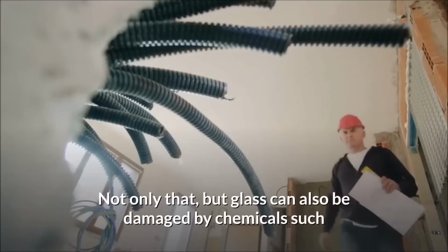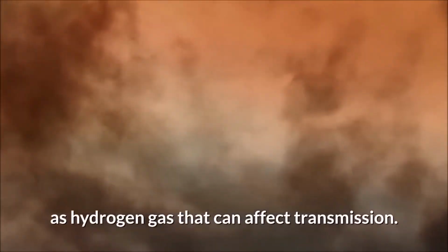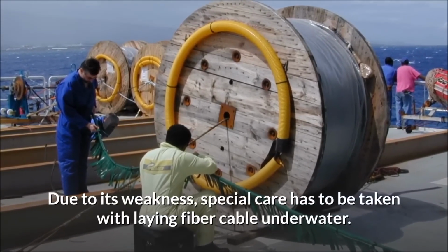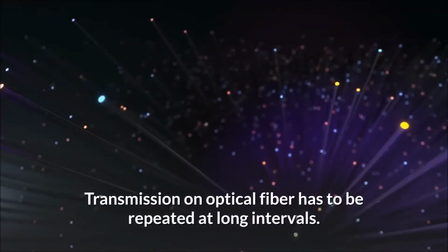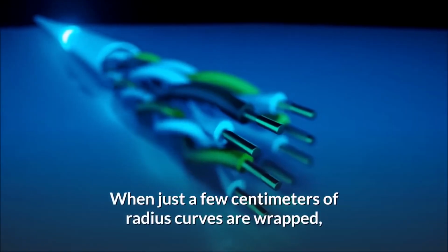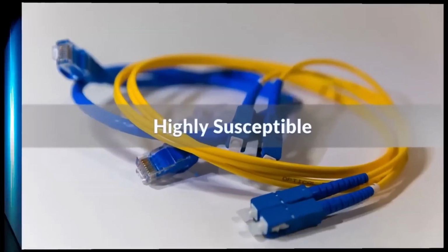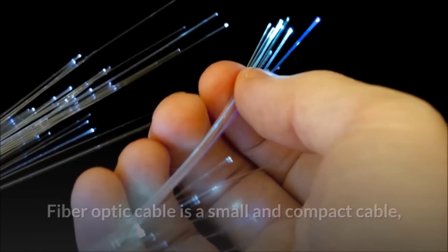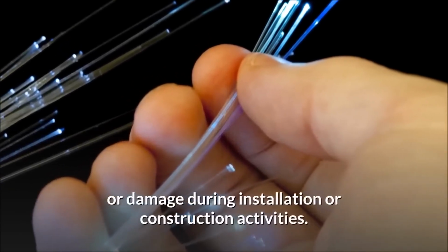Not only that, but glass can also be damaged by chemicals such as hydrogen gas that can affect transmission. Due to its weakness, special care has to be taken with laying fiber cable underwater. Can't be curved. Transmission on optical fiber has to be repeated at long intervals. When curves with a radius of just a few centimeters are made, the fibers can be broken or the transmission can be damaged. Highly susceptible. Fiber optic cable is a small and compact cable, and it is extremely sensitive to cuts or damage during installation or construction activities.